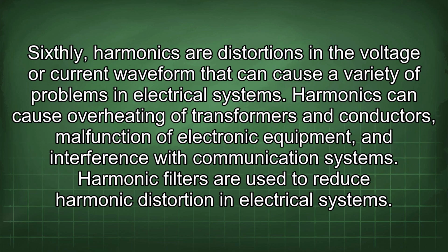Sixthly, harmonics are distortions in the voltage or current waveform that can cause a variety of problems in electrical systems. Harmonics can cause overheating of transformers and conductors, malfunction of electronic equipment, and interference with communication systems. Harmonic filters are used to reduce harmonic distortion in electrical systems.